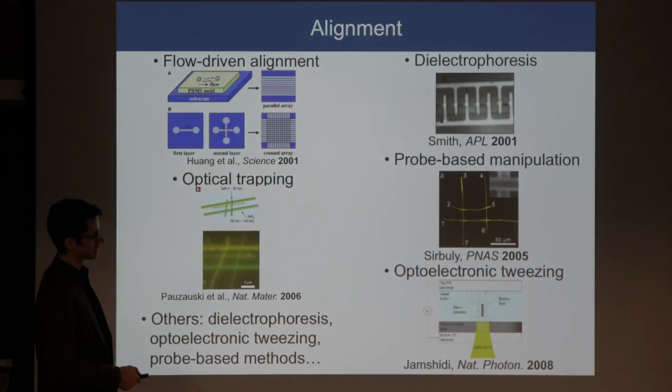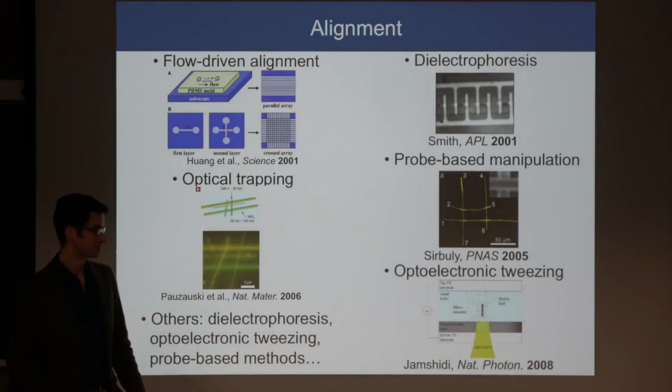And we have optoelectronic tweezing, which is kind of like taking optical tweezing and dielectrophoresis at the same time, where we create a dipole in a photoconductive layer that produces an electric field within a liquid solution, and then we create this dielectrophoretic structure, but we've induced it using an optical signal.